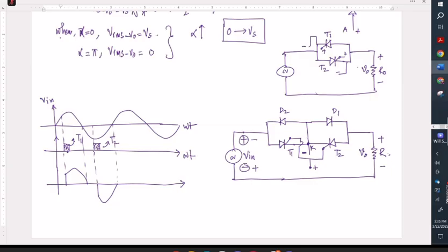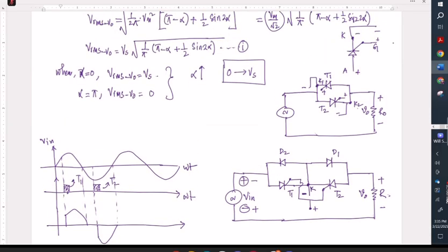That is because here, as you can see, this thyristor has a cathode here. So that is your K1 and this is your cathode K2. In order to turn this thyristor on, you need to provide a gate pulse with respect to the cathode. So if you want to make thyristor T1 on, you need to provide a positive gate pulse G1 with respect to this cathode K1.